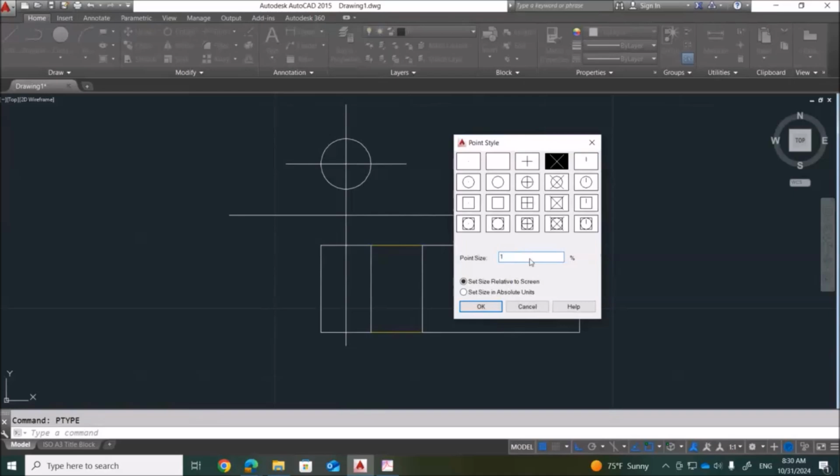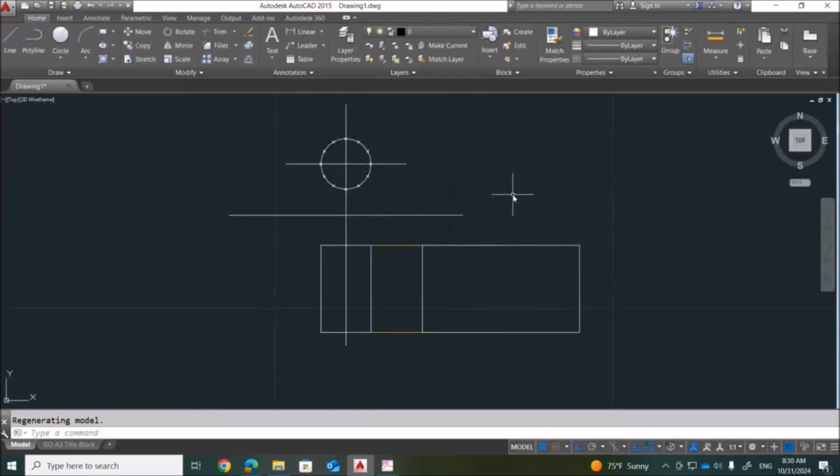Now if I make it 1, enter. 1 is okay, good. It should not be too big, it should not be too small. You should select that point. Again repeat the command divide, D-I-V-I-D-E, divide, enter. Select the object, this line, and divide it in 12 parts, enter.